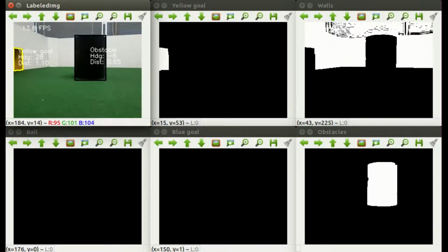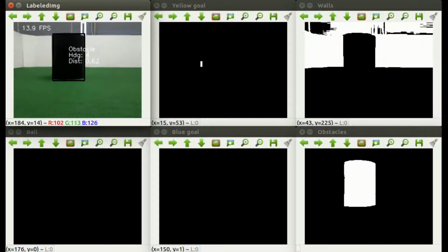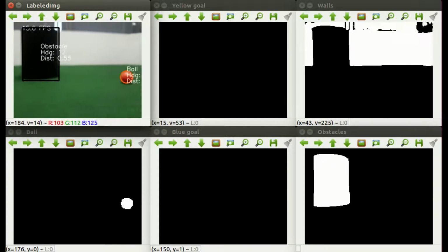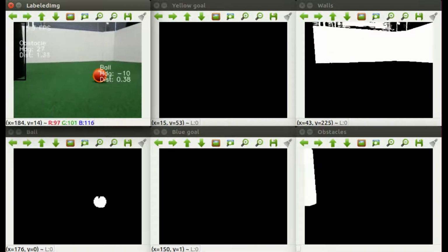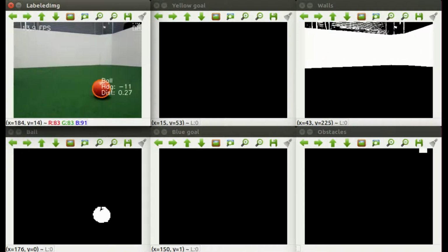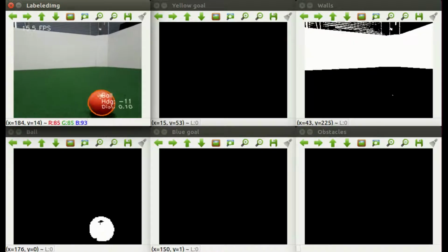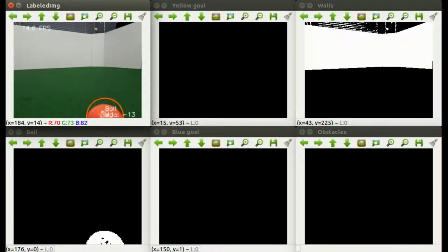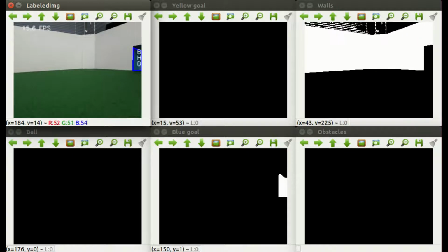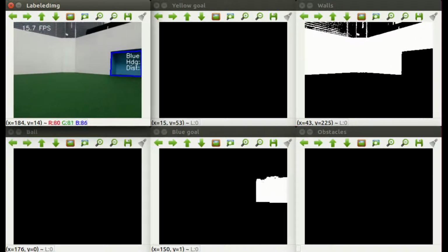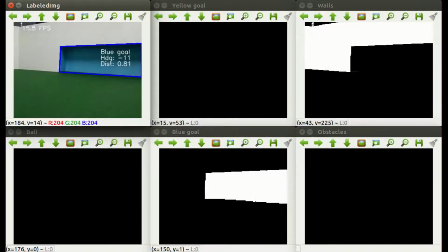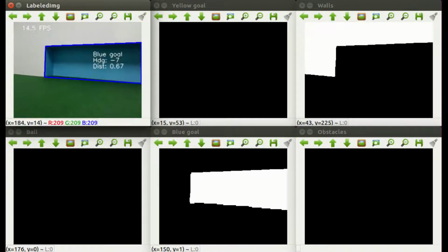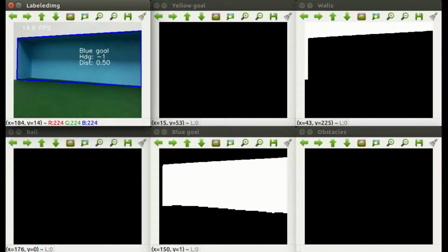Although we can segment desired objects, we also need to determine the bearing and distance to them so navigation can do a proper planning. To do so, we determine the visual size of these objects based on the data in the mask, for example, by approximating the ball as a circle or obstacles as rectangles. Afterwards, we can determine the bearing and distance based on measured visual dimensions and known real dimensions of these objects. This information is provided to the navigation subsystem to allow planning of movements and actions of the robot to score goals.